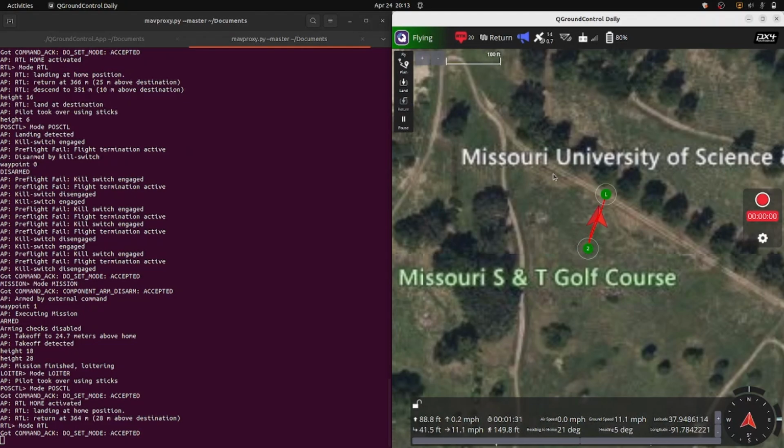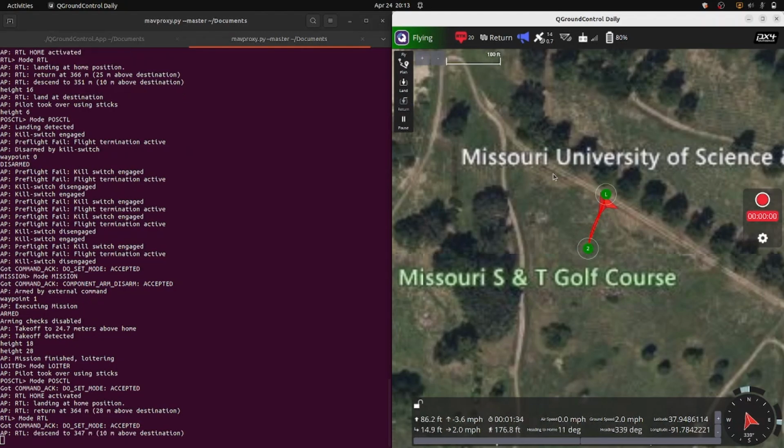The ELRS transmits digital RC control messages, and these messages are translated to analog to go into the input on the carrier board of our drone. Our telemetry radio uses a digital data of MAVLink to transmit messages from the ground control to the actual drone, as well as our flight computer sending those digital MAVLink messages to the autopilot.